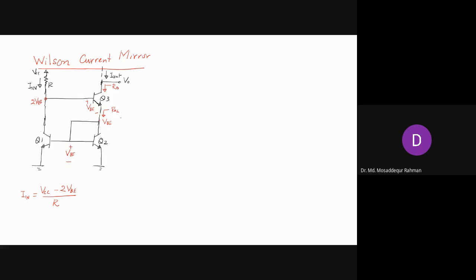Now R02, you see that this is connected to Q2. So obviously we have this small r naught between collector and emitter. And then this is another branch connected to the base. So you need to see what is the resistance coming from this side. Now this side is connected to the 2 bases, and that is the resistance that will contribute to this total resistance.